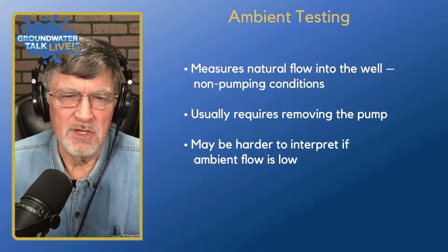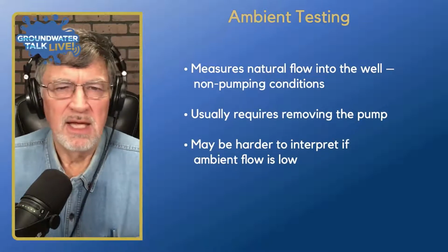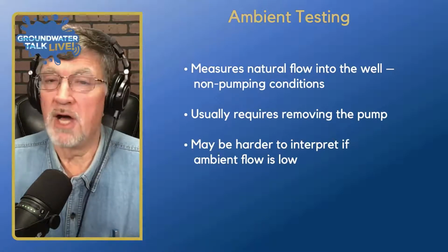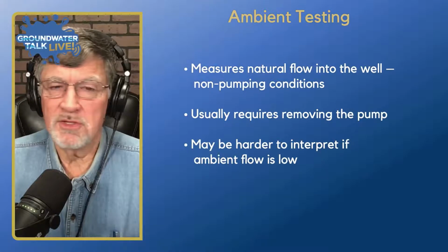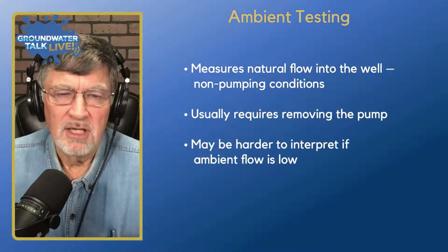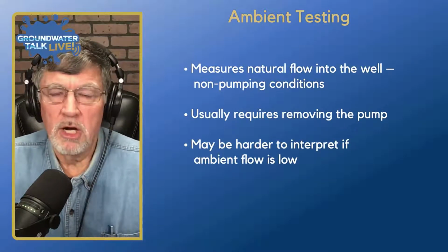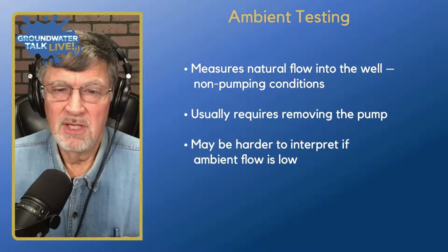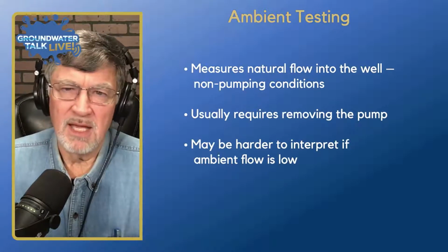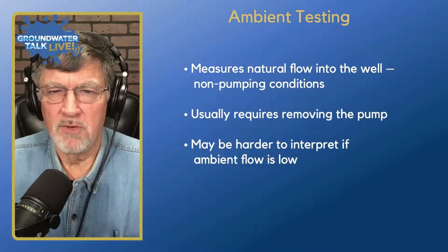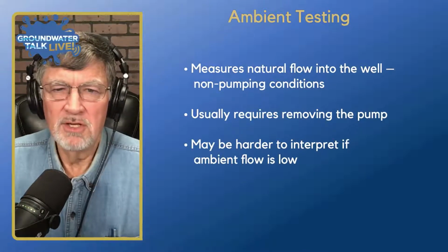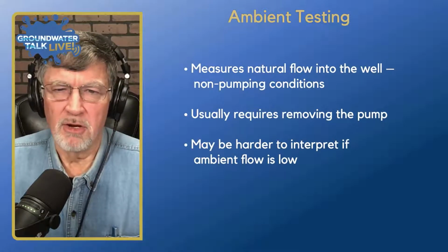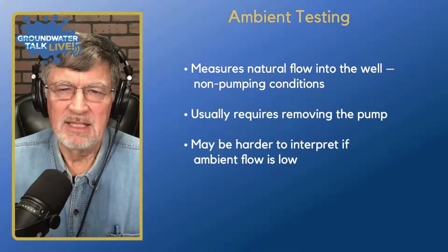There's ambient testing and dynamic testing. Ambient testing measures the natural flow into the well under non-pumping conditions, and this is going to be important to determine how things are flowing into the well when we're not pumping, so your natural state of things. Usually any of this testing is going to require removing the pump. The ambient testing, so we can have free access to the well, you're going to remove the pump, and then we can take our meters up and down the pump.